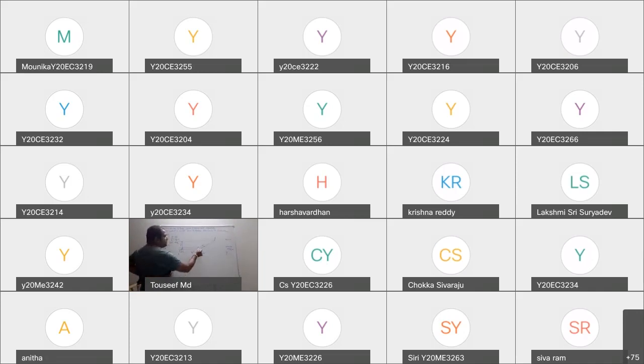Okay, why? Because when the front view point and top view point are both known, only then is that point considered for the center of rotation. So I know my VT and V, the full-fledged point is known. So that is the point to consider for the center of rotation. So VT as center, VT B dash as radius, draw an arc up to the locus of VT. Remember, wherever you take the center of rotation, if you start rotating with that radius, you have to rotate up to the locus of that point only. So this becomes your B2 dash.